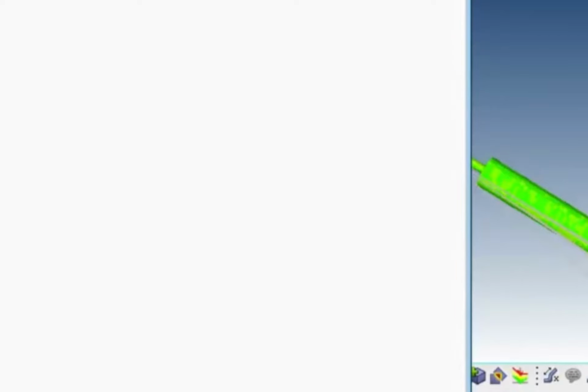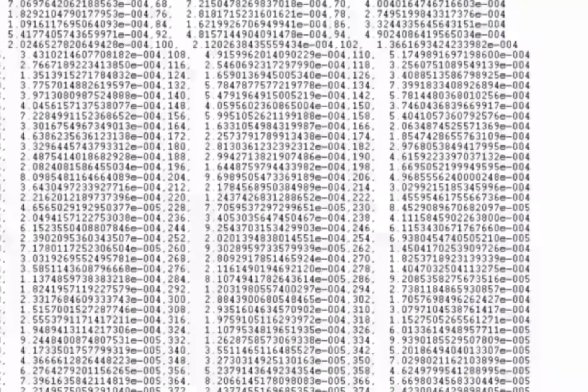So we have the PSDs in this file. If I open one up, you'll see these are also in Nastran format, but they're double precision entries. So if you're familiar with Nastran random input, this is what's called a VRAND PS entry. And VRAND PS specifies the contributing PSD inputs to the system. This is a 3-input system, so I've got 3 direct PSDs plus 3 cross PSDs, which are all complex. So altogether, I've got 9 contributing PSDs to include in this single file, and they're all written